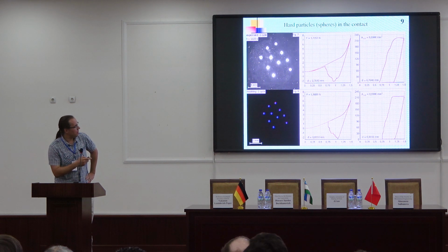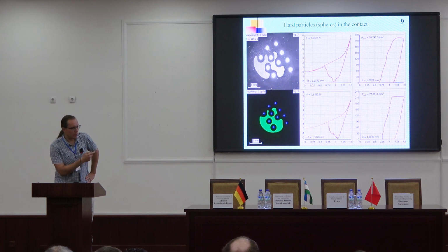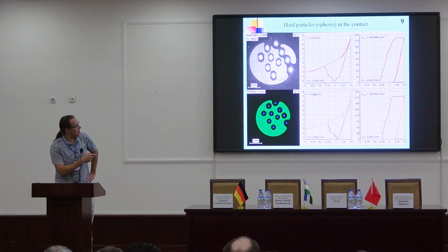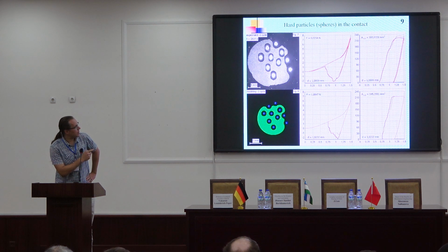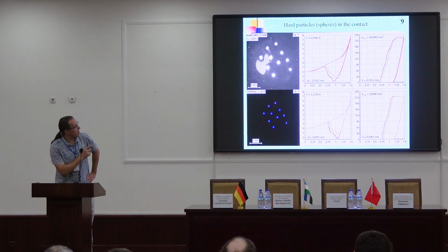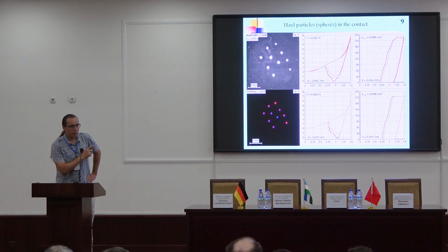And you can see here also some difference between experiment and simulation, but in principle we have observed the same curve. For example, it's interesting at the indentation depths. At the indentation phase, firstly, the adhesion is very weak, but we have an increase of contact stiffness. This force and indentation depth relationship is non-linear at first. After this, we have observed a linear dependence.